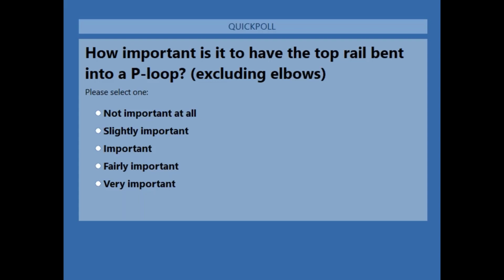With internal vent holes off for top rails and mid rails, will the base plate still get a vent hole? Yes. There is an option when you have that turned off. Once this poll is finished, I can go ahead and show you. In the galvanized vents, if you have internal checked off for post, an internal and connection plate becomes enabled. So I'll go ahead and close this poll.